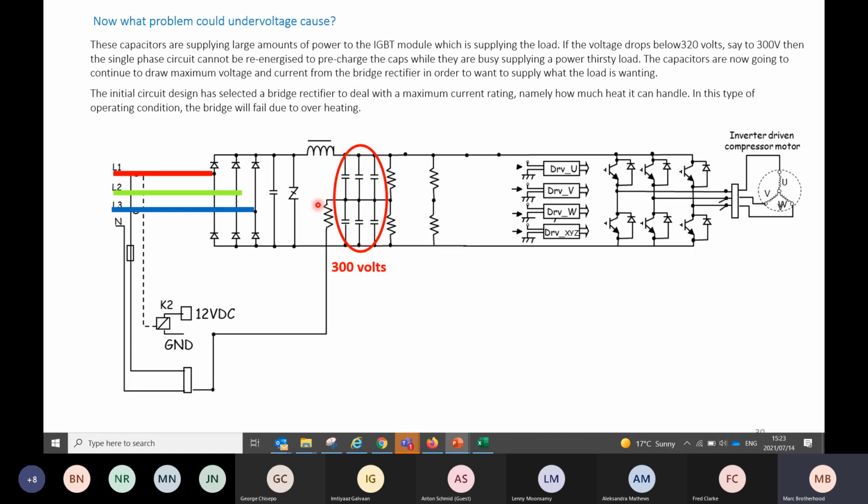When they drop to 300 volts, because I'm not getting enough pressure to charge them, because this phase is being drawn because of a bad design on too much single phase, I cannot quickly re-engage this circuit to charge the caps, because that means I have to open this relay. If I open this relay too quickly, there's going to be a lot of flashing and arcing, and the relay is going to burn. Then I have to quickly charge these up, disconnect this neutral circuit, relatch this relay. It's too much happening, too much arcing, sparking.